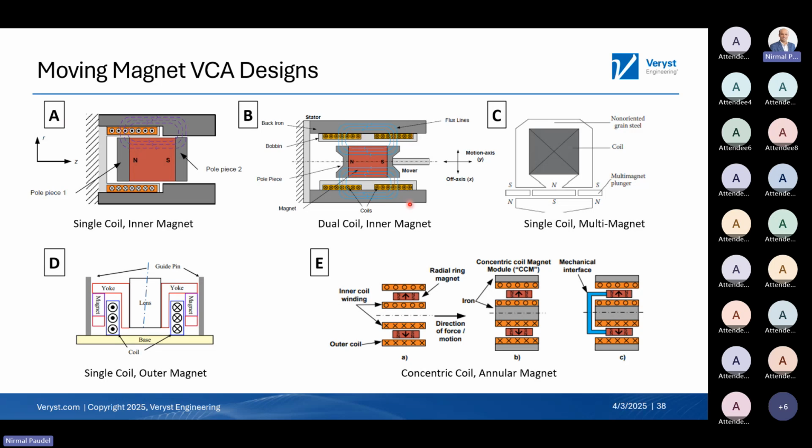The direction of current in those two is opposite. So if the force from one coil is attractive, the force from the other coil will be repulsive, so the net effect is doubled. At the same time, there is a clever design on the magnetic pole with a conical shape, which makes the force profile flatter.